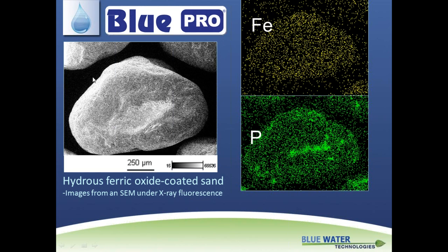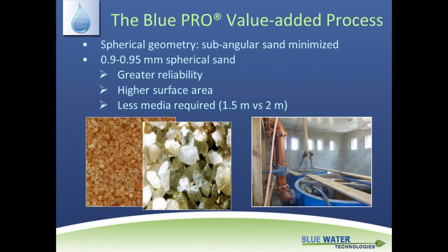With adsorption, you're not building any particle size in the water going into this vessel, into this process. You're simply coating the media, and you have free flow of the water across the surface of the media, and that's where your chemical uptake of trace metals happens. So that's a huge difference between an adsorptive-based Blue Pro system and a coagulation followed by filtration process.